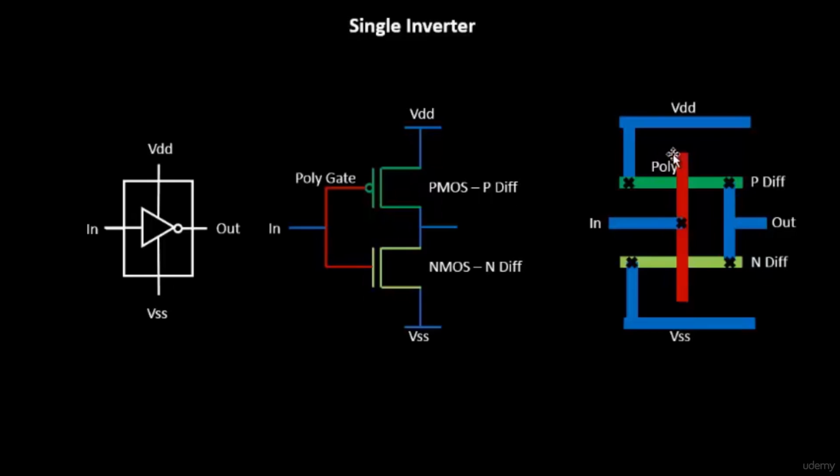Okay, and if you look into this particular gate, this is your PMOS gate, this area is your NMOS gate, and this is the gate length. I have talked about the term gate length before. This basically defines at which node you are, whether you are at 20 nanometer or 30 nanometer or 45 nanometers, 65 nanometers.